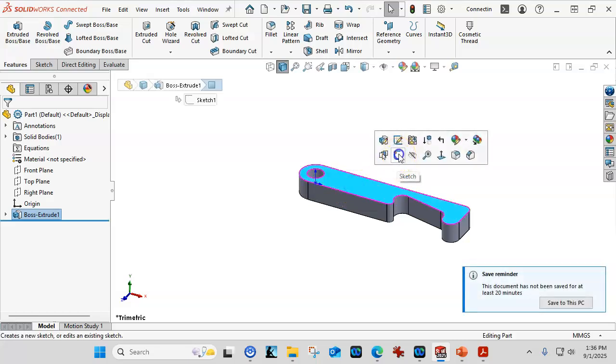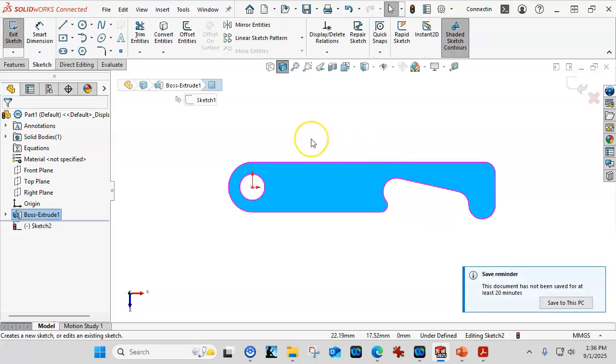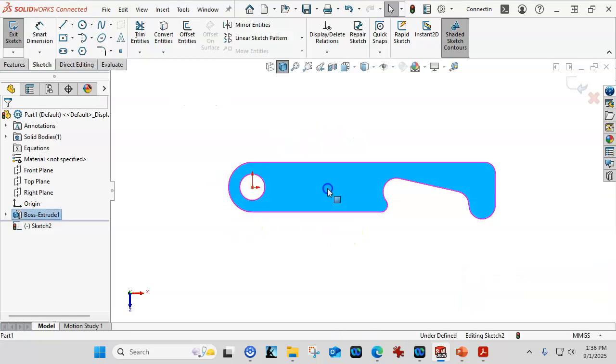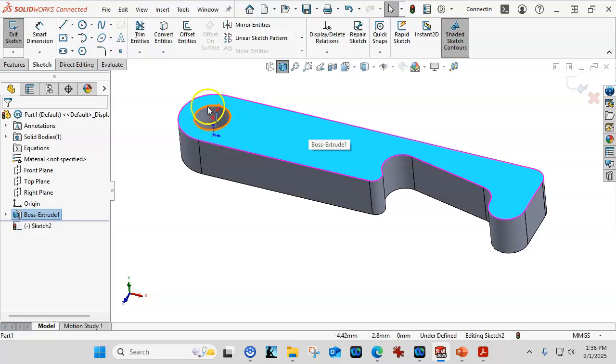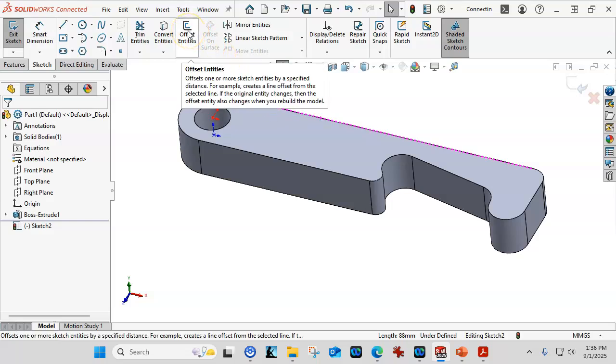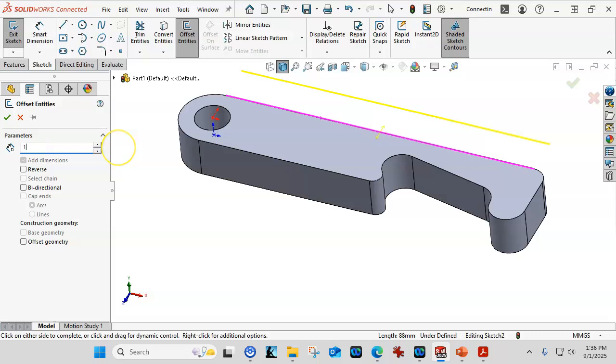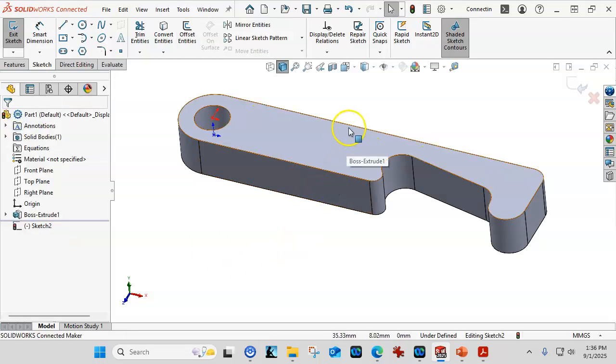We go ahead and open up a sketch. Now, the center, we don't want to offset. So I don't really want to offset on the face. If I have the face selected, it may bark at me for having the not connected entity. So if we go offset 1 millimeter and I have the line, we're going to reverse the direction, and it is not letting me select the chain, so that's interesting. I'm not sure what I got there, but let's go ahead and X out of it.